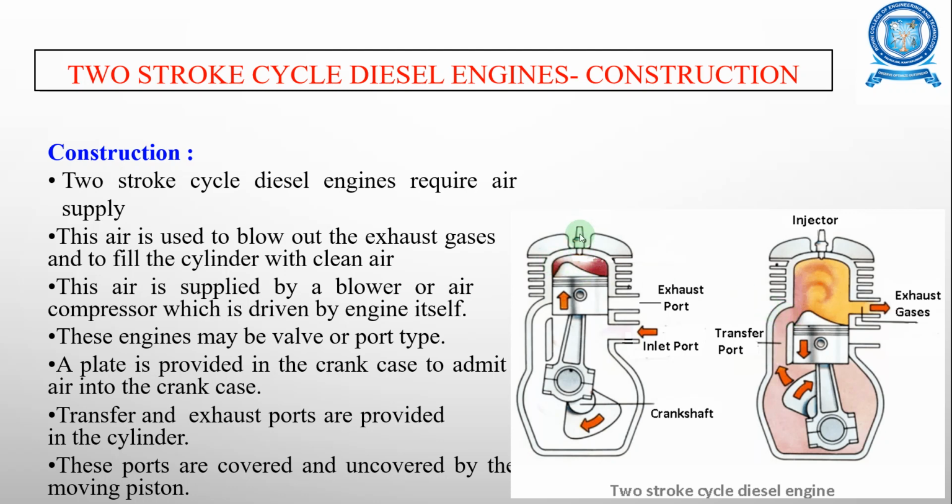And this is the fuel injector. Since it is a diesel engine, instead of a spark plug, you will have a fuel injector in the cylinder head. And these are the air-cooled fins by which this cylinder is being cooled. This engine cylinder is cooled by means of air flow.